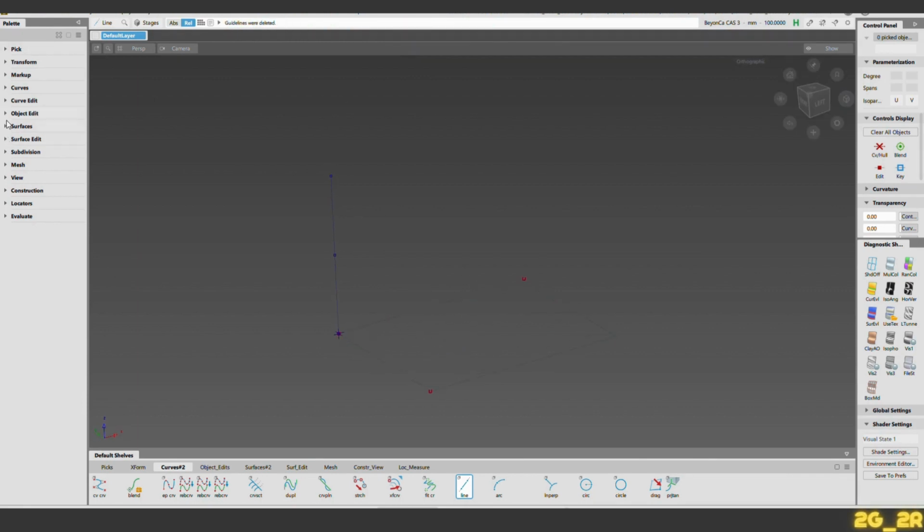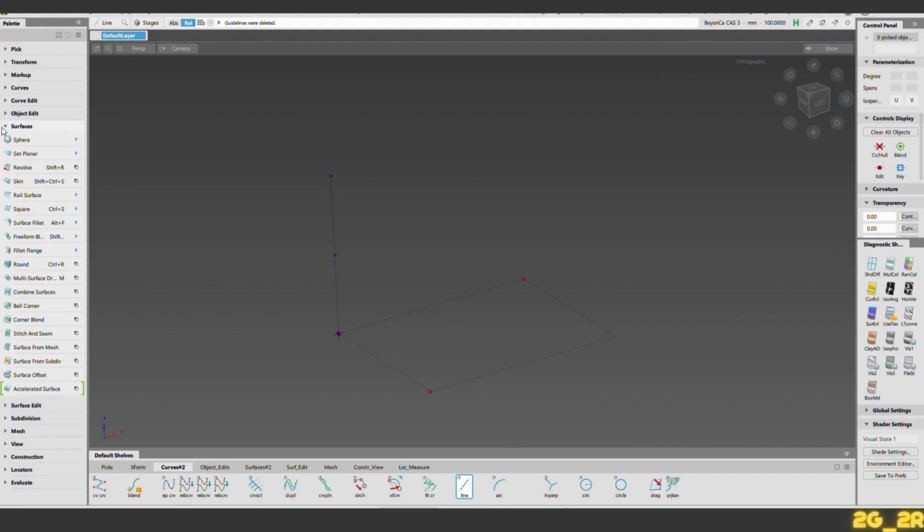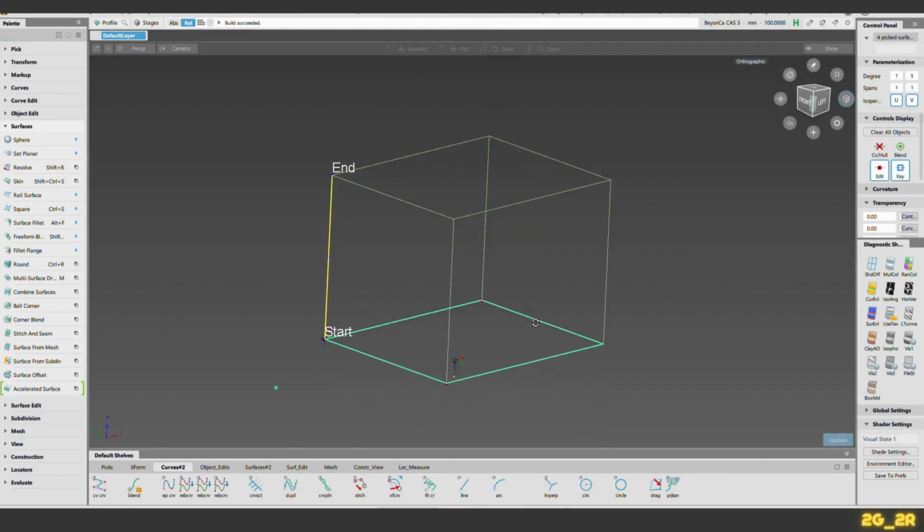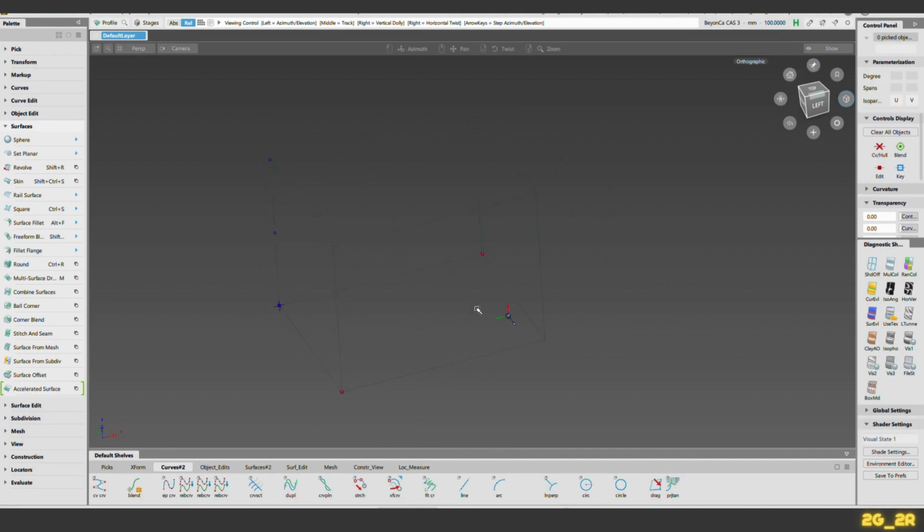For that, one of the easiest ways to do that is we can take a profile. That would be the profile tool. For me it's P. If not, we can look it up in the surfaces here. And we take the edges of the surface that we've just built, and then we just extrude them. So we accept them and we extrude them along that trajectory, and we build that up. And now we have an open box,